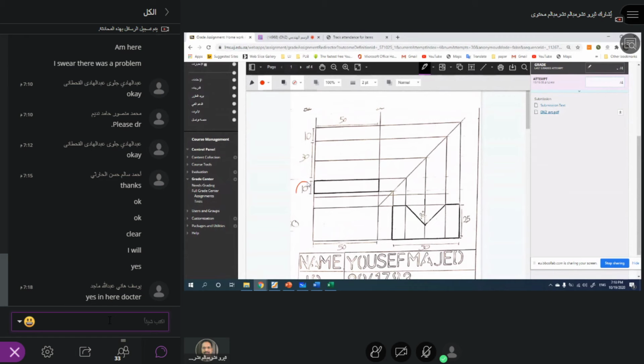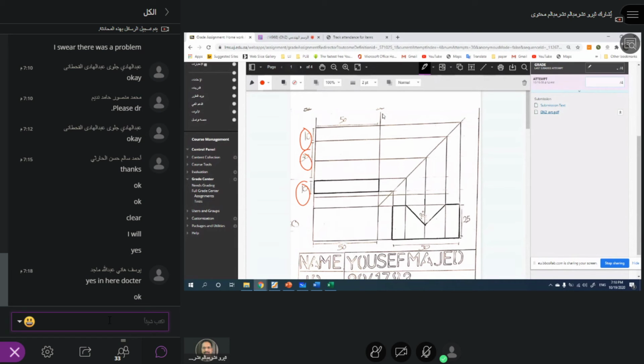So only dimension next time. Be careful, okay? I'm sure you know now how to draw it. Take this away and draw this cleanly. You give 10 millimeters here, and then write it. This is 50 millimeters. So you have to give 10 millimeters here, and then you draw it neatly, and then make your arrow mark here, and then you write 50.